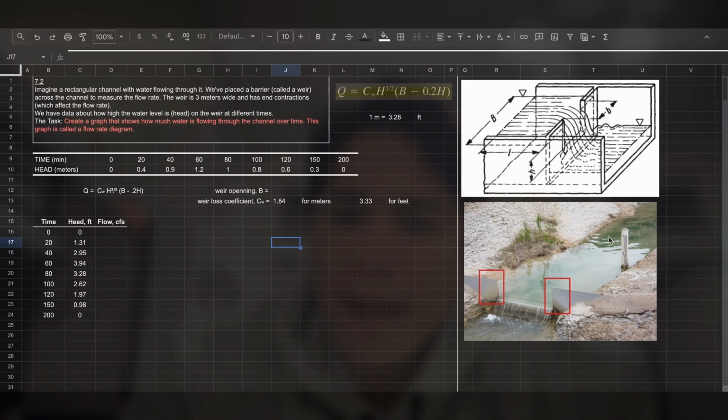So to normalize this, we can create a weir where we already know the width of the opening, and then all we need to do is calculate the height through the opening. So we go from a varying shape into a shape that we are more used to, and it's going to be easier to calculate how much water is flowing through this opening.